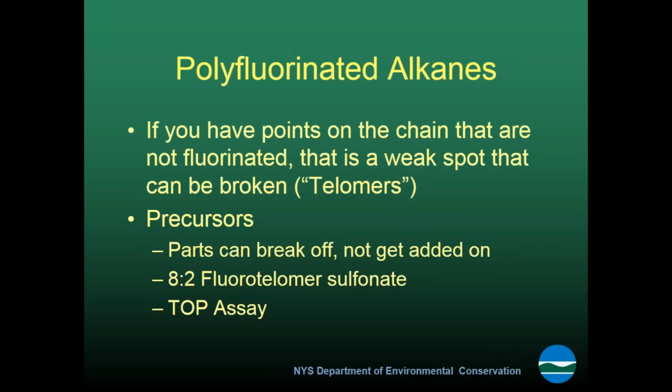The polyfluorinated alkanes, the ones that aren't fully saturated, will break down, and as a result, you can end up with different compositions in your groundwater plume down gradient as the polyfluorinated alkanes break down into smaller perfluorinated compounds. You can do a test called the total oxidizable precursor assay, where they take a sample, oxidize the heck out of it, and then retest it.